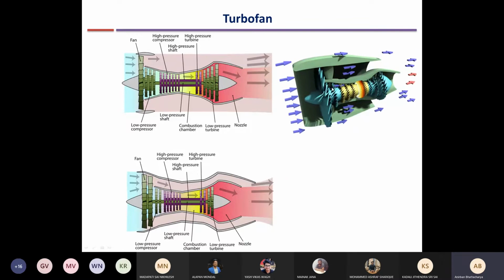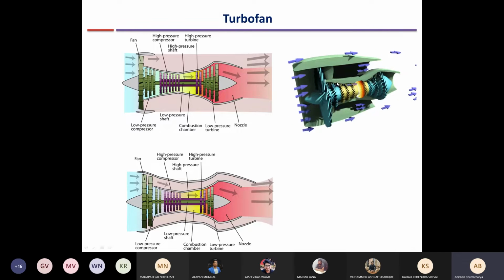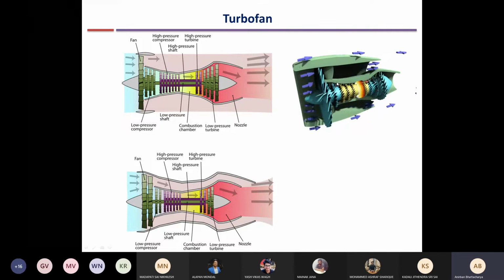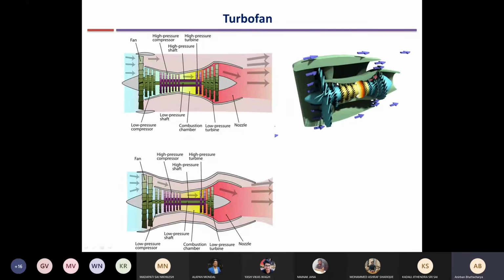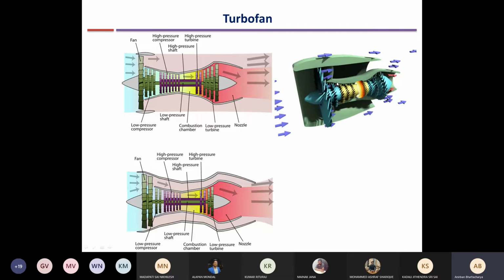Okay. So these types of engines are very suitable at near the sonic velocity or just subsonic velocity, like Mach 0.85, 0.9, which is typical for very large passenger aircraft. All the passenger jet aircraft that you board, say 2-engine aircraft, I think for most domestic aircraft, it is 2-engine aircraft. For large international aircraft, you might have 4-engine aircraft like say Boeing 747s or A380. So all these are turbofan engines, very large turbofan engines.